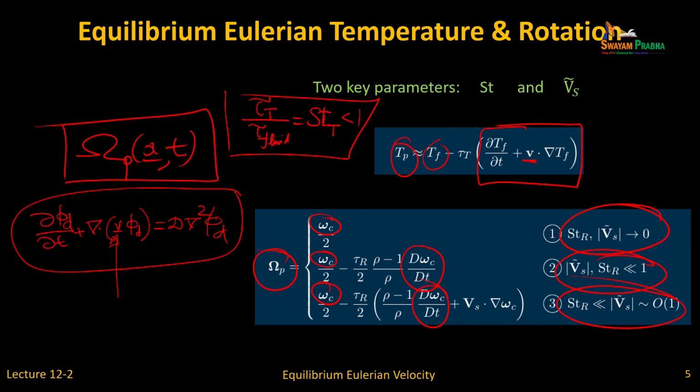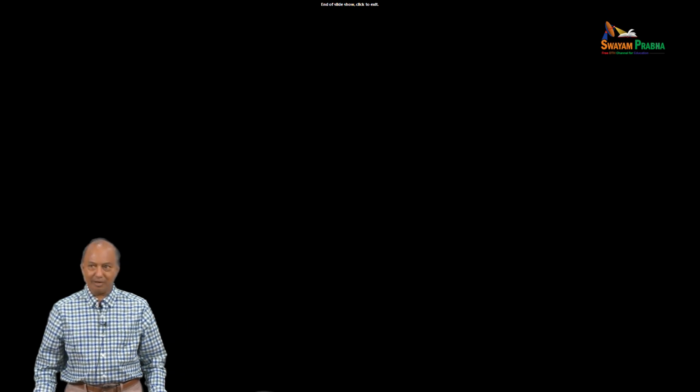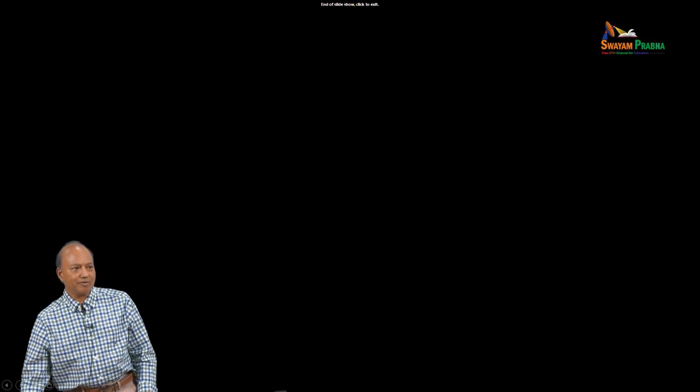Now, this all does not work if the Stokes number is 1 or above. It is good only for small Stokes number. In general, for Stokes number 0.1, 0.2, you may not even need Euler-Euler. If Stokes number gets closer to 1 or a little more than 1, then you must do Euler-Euler. If Stokes number is really large, you could do Euler-Euler, but Euler-Lagrange may capture those variations better. Okay, with that, I am going to stop for questions.